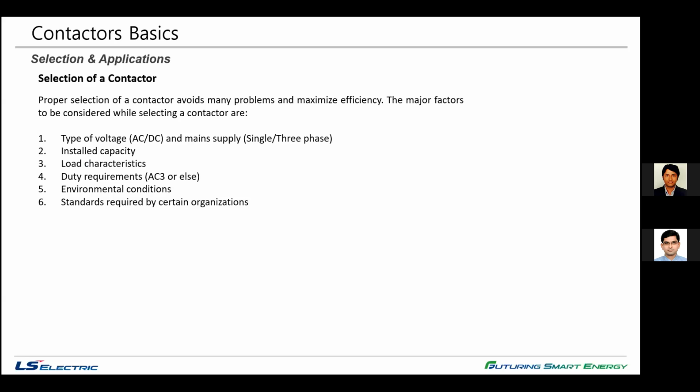Then environmental condition. Normally we are providing normal environmental condition, but sometimes it is a hazardous application as well, so you should be aware. Then the standards. You are supplying for the IEC standard or the NEMA standard. Normally in this region, we are supplying mostly IEC standards.